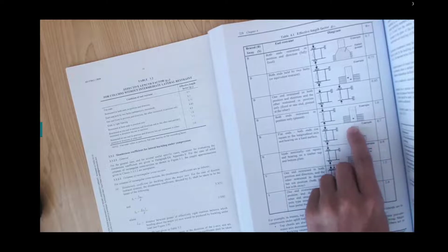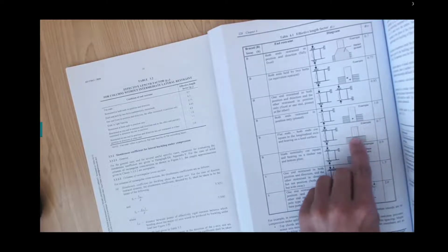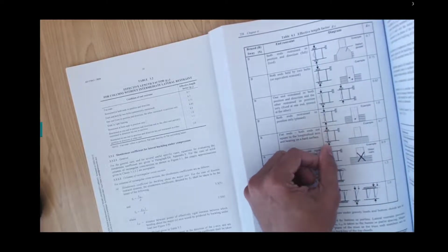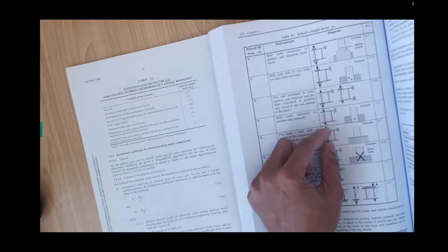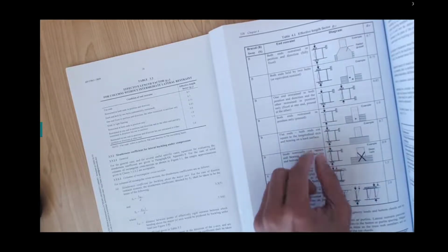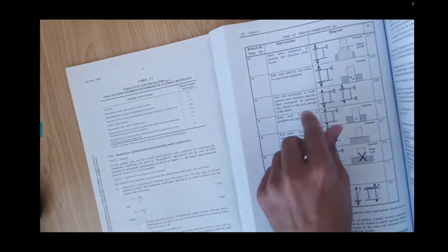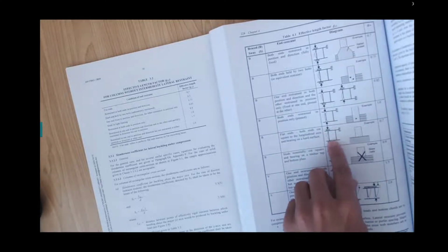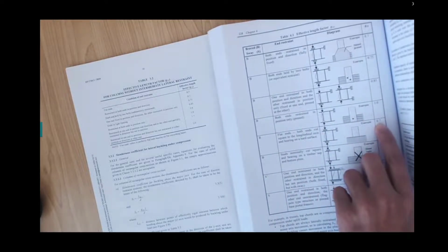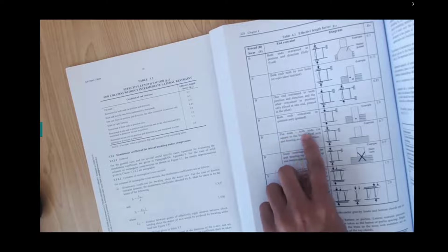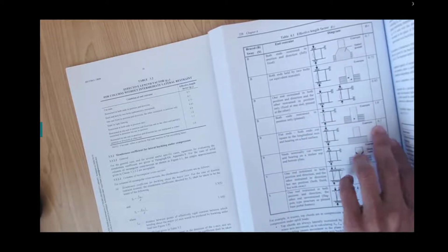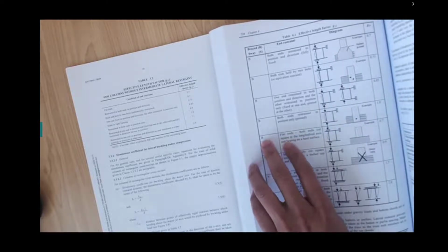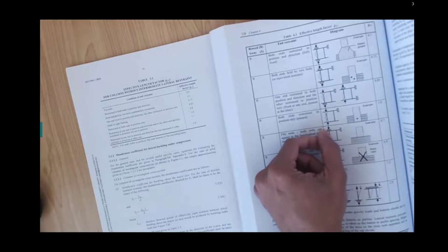So let's say you have this flat surface. You can see this is flat, and it's just like a column, and it's just fixed. There is no rotation, there is no moment. It's not going in this direction, it's not going up and down, it will not have a rotation at this end. So that would be good. So you have this 0.7 if you have this flat end kind of restraint, which is 0.7, and that is part of the braced columns. Braced columns mean these joints will not move.